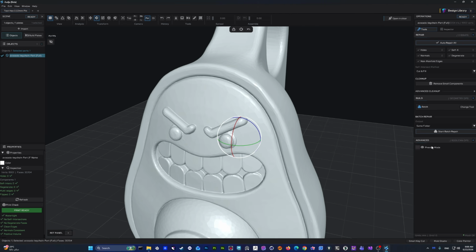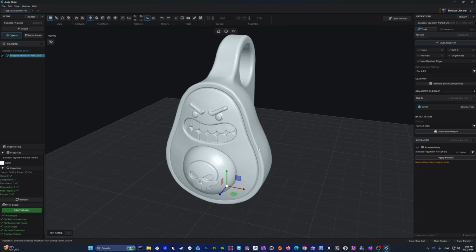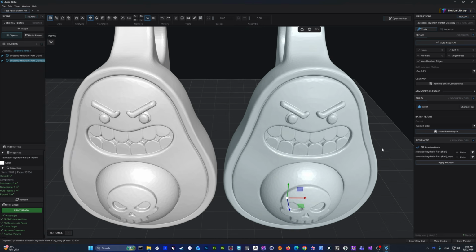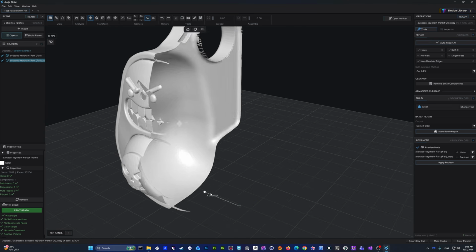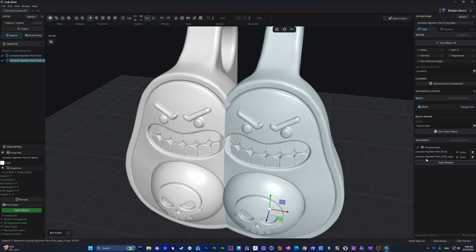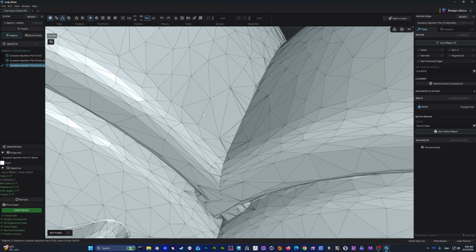And we have here the advanced, that's basically the Boolean stuff. Let's say if you want to duplicate the model and you don't want to come here and press duplicate, you can just press Control and left click and drag like this. All right. So you can control from here. If you move this, as you can see, or I want to make it a union like this. You press apply. So you can see if I open the wireframe,